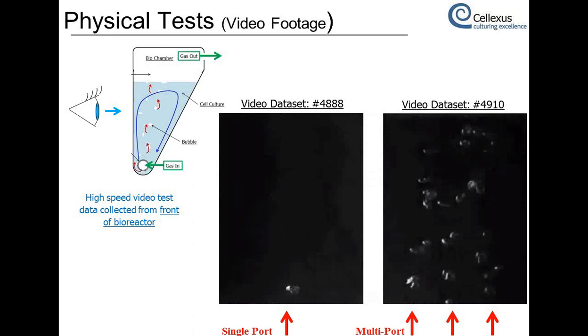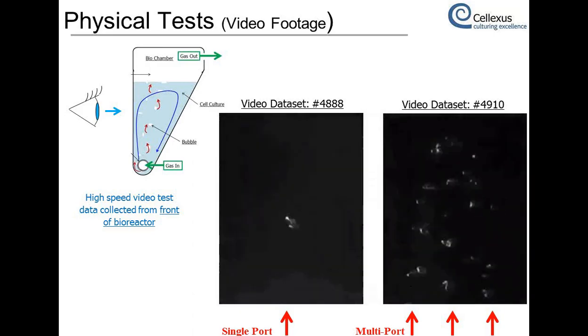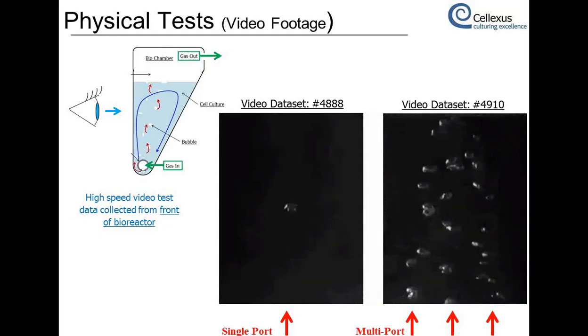Hopefully you can see some of the animations coming through this moment. As you can see the bubbly flow coming through. And we monitored these bubbles over time. And what we ended up doing is graphing the physical data, the equivalent circular diameter and the aspect ratios. The equivalent circular diameter, so what we did is as the bubble was moving up the column, we tracked it and analyzed the area or cross-sectional area of the bubble as it moved up.